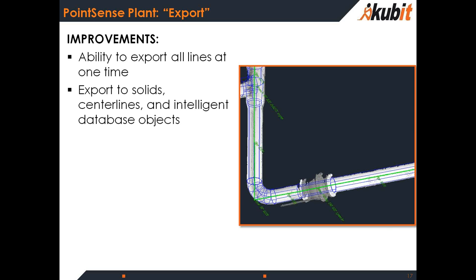We added additional export options. One is to export to AutoCAD 3D solids, and you can separate that to its own layer if you want to. We did this in case anybody wants to do a simple clash detection, or maybe you want to bring a simple solid into Navisworks or another design product. The AutoCAD 3D solid model is one of the most exportable formats out there, so it's a good option for the user, just in case they need to deliver something to a client that's using a different product, or they want to take those results somewhere else.